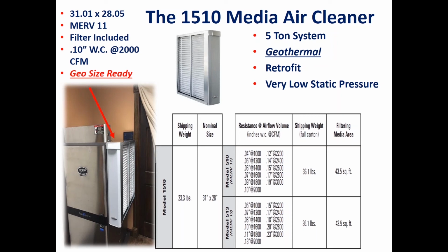It's designed for very, very low pressure drop. So this could be a 5-ton system or a geothermal system where they have very large return openings. But I wouldn't limit it just to that. This can also be used in any situation where you need to have very low pressure drop.